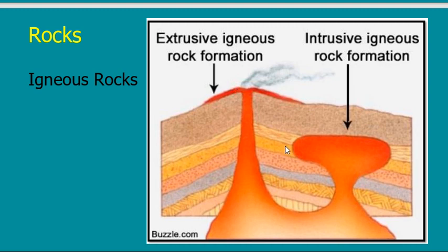Imagine here as a geotechnical engineer, when we speak about strong rock, I don't care whether it is lava or not lava. I care for the material. When it is extrusive, then it means that it was cooled on top of the ground. The name of it is lava. So it will be weaker than the intrusive, which is below.